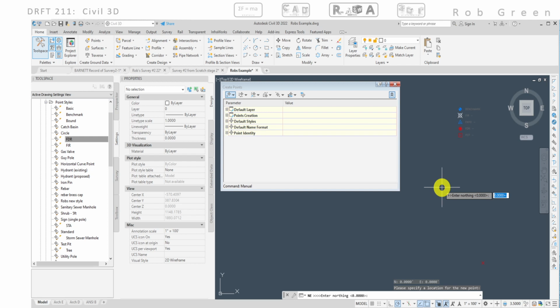And all of those elevations are 0, and the description is described in the table. So as an example, point 1 is going to be negative 101.07, enter. Negative 46.01, enter. The description is going to be FKPD, enter, and the elevation is 0, enter.